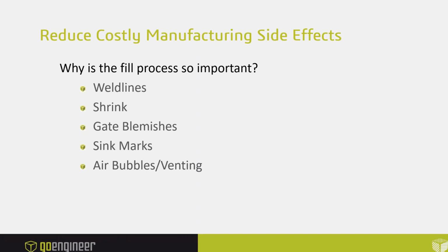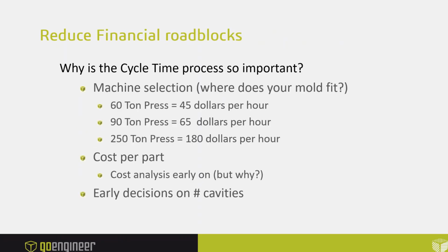Gate blemishes, sink marks. Sink marks are ugly. How much texture do you need? How much sink mark do you have? I don't know, right? But those are the questions that we should ask ourselves when we're making our parts and designing them and deciding to manufacture them. And then air bubbles and venting.